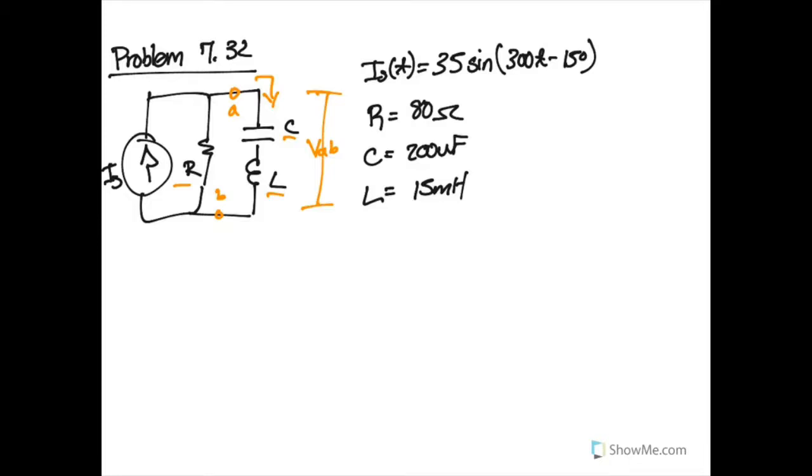There are a couple ways we can go about this, especially if we think about this in terms of an old resistor problem. If we want to know the voltage AB, then as a sort of first order problem, we could go about solving the current through the resistor, and then I times R gives us the voltage across the capacitor and the inductor. So approach number one would be to find one of the branch currents and either multiply by the impedance across the resistor, or figure out the other current and multiply by the impedance across the capacitor and the inductor.